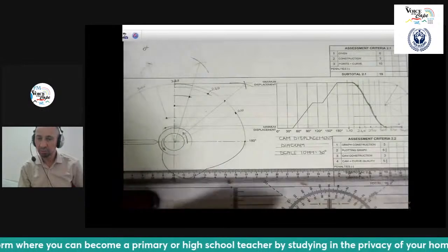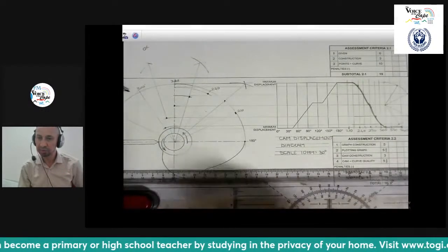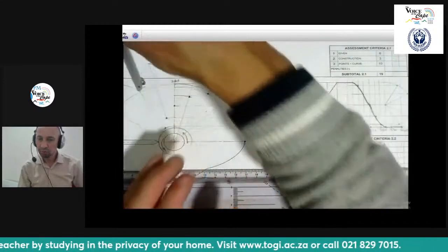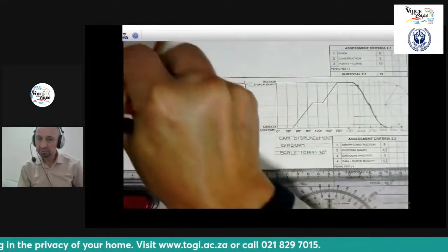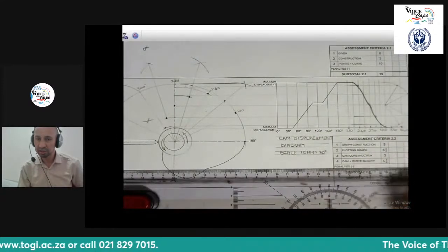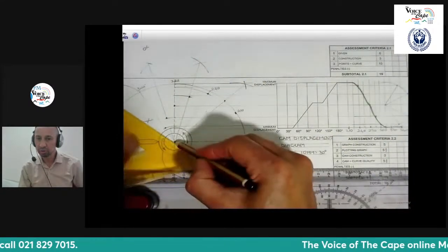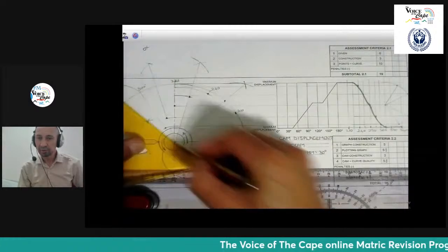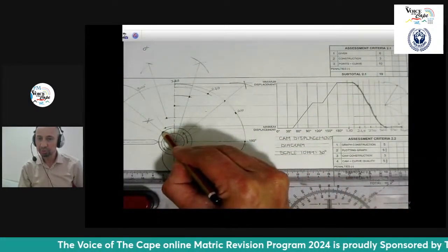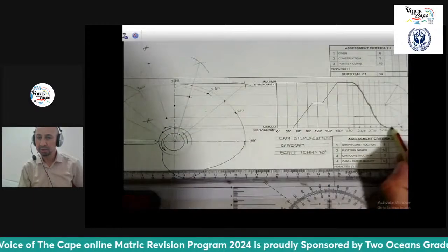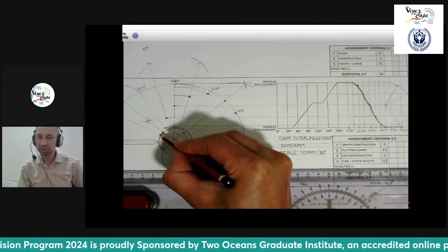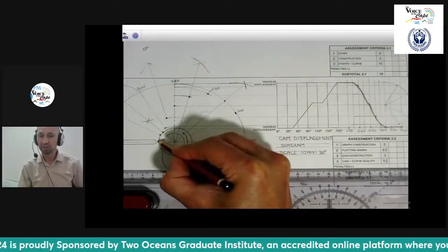It's on the circle on my minimum, because it's at my minimum here, so it will be on my minimum there, right? But you obviously need to halve that space as well, which I'm doing right at this moment. There you will see I halve that space on the inside. There it is. And then I'm going to draw a line exactly at that very point here. That is where my plotted point is going to be at its minimum. And then you will just have the two other points that are now stationary as well, which are dwelling. And there you have all your points.